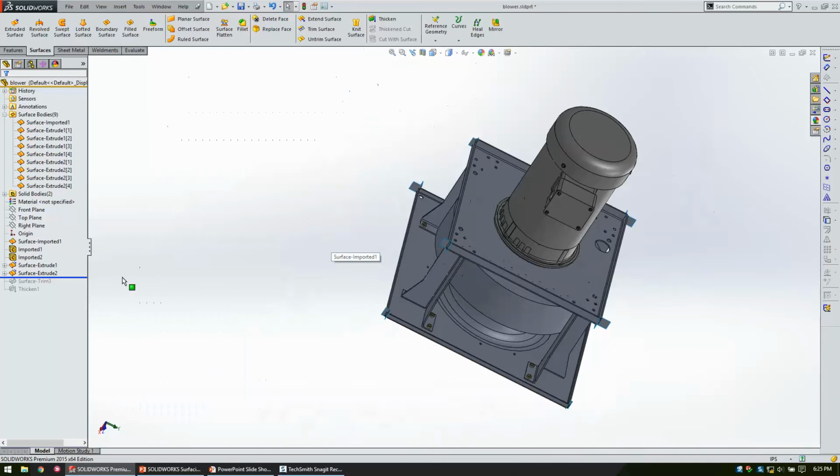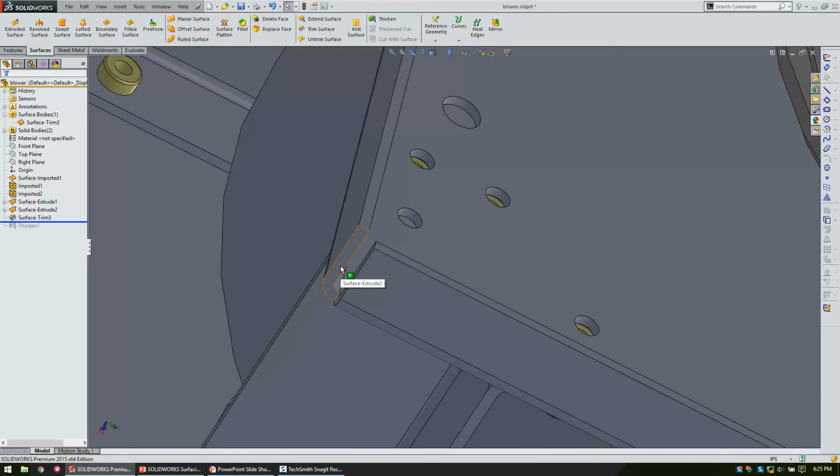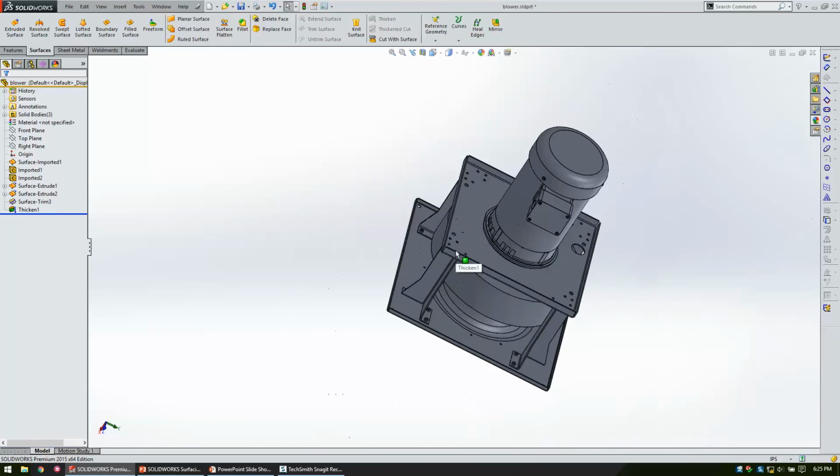So to get it to work properly, once we figured that out, you had to draw that around all 8 corners, cut all 8 corners away at once, knit that entire thing together all at once, and then we could thicken it and create a solid. But if you couldn't find all 8 corners, you would play with it forever.